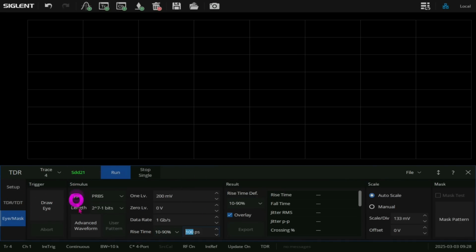So first thing is asking me what kind of PRBS signal I want to apply. Now generally you want to apply a fairly long PRBS sequence in order for it to have a fairly complex frequency response, so you get a true representation of your ISI and jitter, but it supports many different kinds of lengths. It's sometimes helpful to go back to lower lengths because you can then tell what the problems are and where the transition densities, for example, make a difference. So let's select the highest one over here.